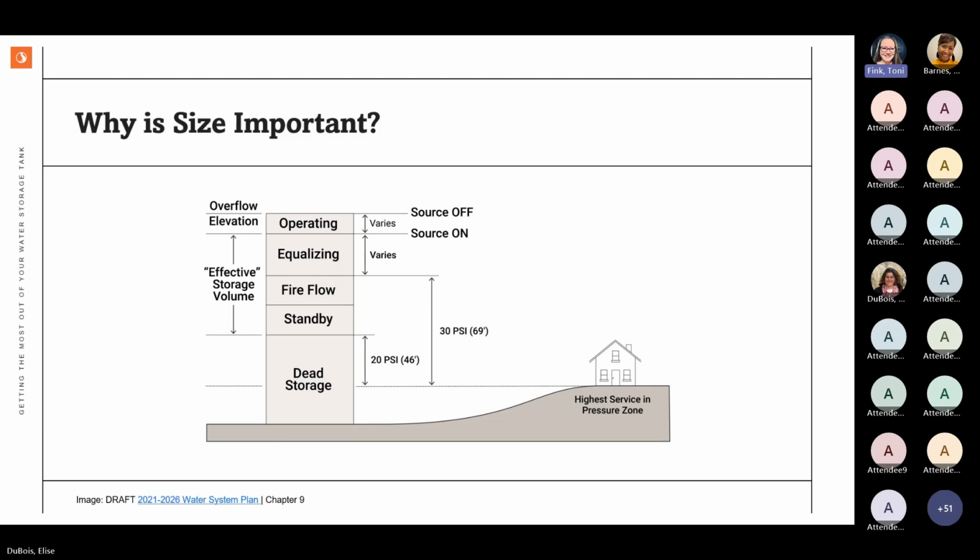All right, so I think you answered the second half of this question about the mixers being modeled, but can you give the audience some of the main design factors that you look at when you're looking at the mixers? Yeah. So first we start off with whether you need active or passive. The only time we really use passive is if you have a clear well or your tank is already showing by the calculations that you're turning over multiple times per day. So most tanks fall into that active category.